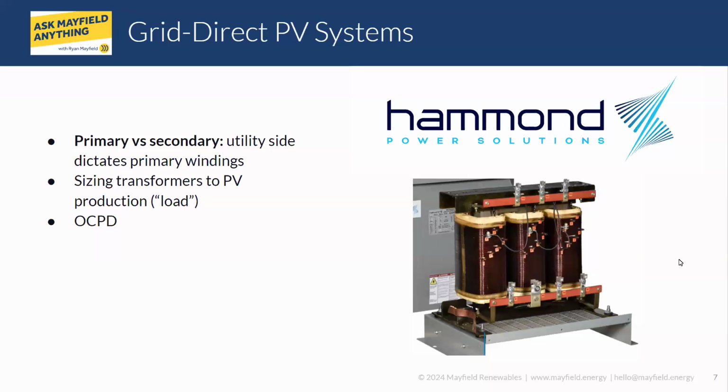We'll show you something else here in a minute, and how our solar design transformers are specifically labeled as such. But the bidirectional functionality is not automatic either. In other words, not all transformers are designed for bidirectional usage. So that's an important designation in these types of systems.